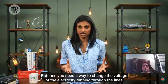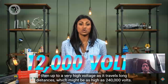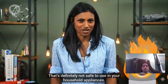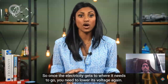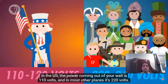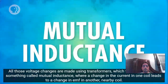But then you need a way to change the voltage of the electricity running through the lines from its original voltage from the generator, which could be around 12,000 volts, up to a very high voltage as it travels long distances, which might be as high as 240,000 volts. That's definitely not safe in your household appliances. So once the electricity gets where it needs to go, you need to lower its voltage again. In the US, the power coming out of your wall is 110 volts, and in most other places, it's 220 volts. All those voltage changes are made using transformers, which take advantage of something called mutual inductance,